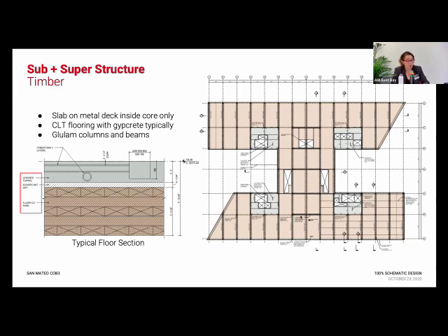In the end, the cost question came about. We have terrible soil at this location. We are in bay mud, and it is as not useful as it could possibly be. So not only do we have 300 piles below this particular building, we had to keep it light. And so mass timber, from a savings point of view, and I say savings intentionally, helped us because of the substructure. As you're exploring materials and trying to judge embodied carbon, don't look at just that one material. If you narrow yourself to that one scope, you're never going to get an apples to apples comparison. Where are the other benefits that you have? In this instance, we were able to significantly reduce the quantity of piers that we had. In addition, we were able to reduce the time of construction, right?